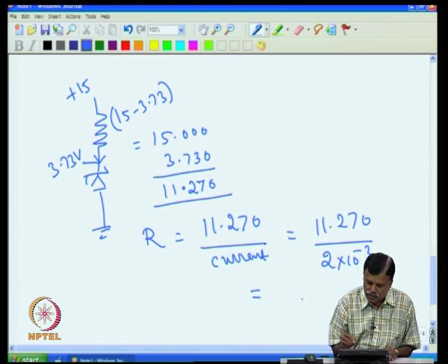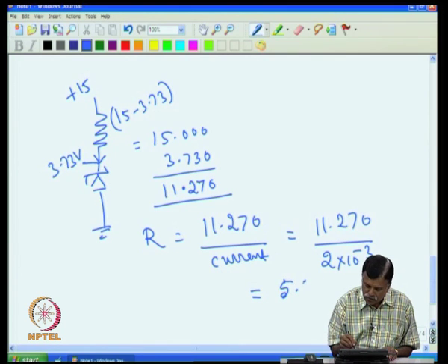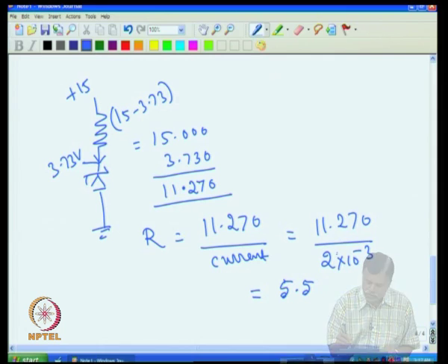That if you convert into resistance, then you will have 5.6 K resistance. If you do this division, you will get 5.6 K. Now, if I look at the nearest value that I can put, 5.6 K resistance. If I put 5.6 K resistance, then I know approximately 2 milliampere current is maintained through the sensor. So, I will put here 5.6 K.